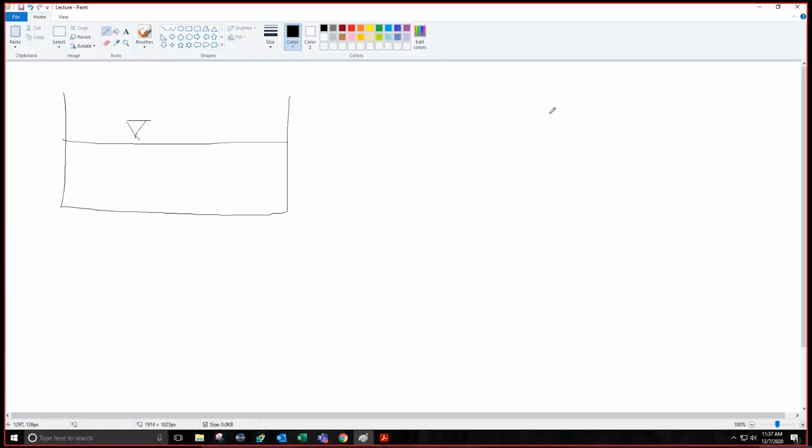So we start, let's say we have a tank and discussed, okay ji, we want to draw a graphical representation of the pressure forces acting on the wall of this tank. We took one wall, let's say the right wall, and we said, okay, this is the pressure distribution. If H is representing the elevation of the tank, at this point pressure is 0 and at the bottom it is equal to gamma H, because this fluid has value gamma as its specific weight and this H is the elevation of the tank.